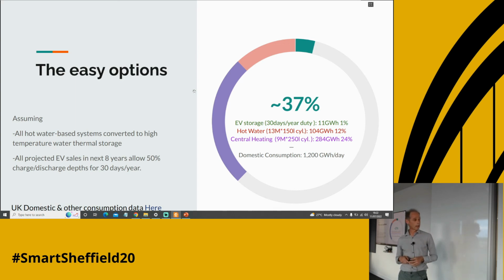but actually they're often compared with water favorably only because water is often not heated up to a very high temperature. There's actually a second problem, which is that heating up water and storing it at, say, 90 degrees is perfectly safe in theory, but if you want to buy a thermal cutout to make a safe system that works at 90 or 95 degrees, you won't get one at your local plumbers, and you probably won't even get one until you go to an industrial supplier. So there's quite a lot of stupid stuff as well to deal with to make this work,